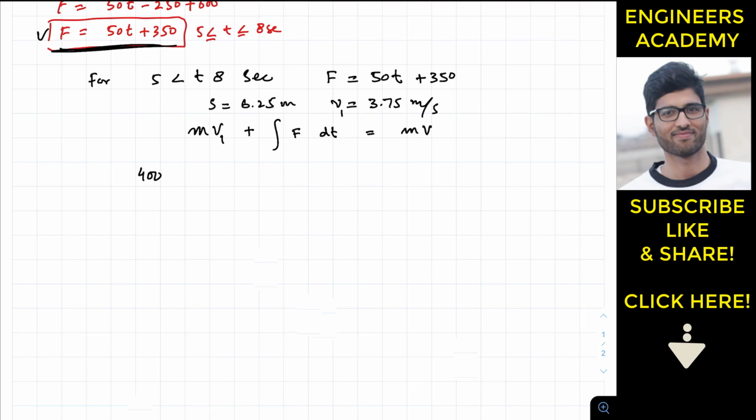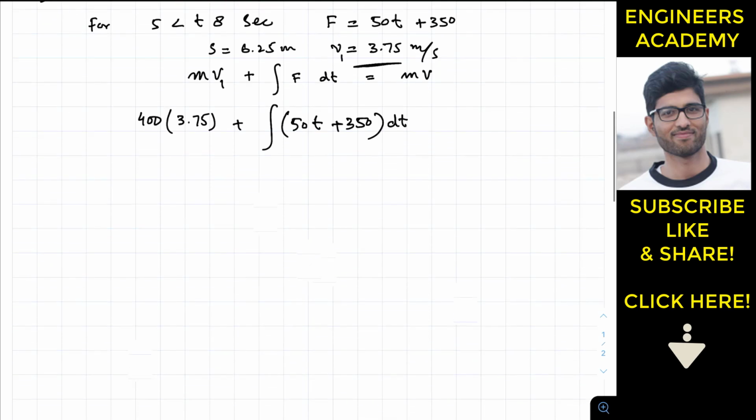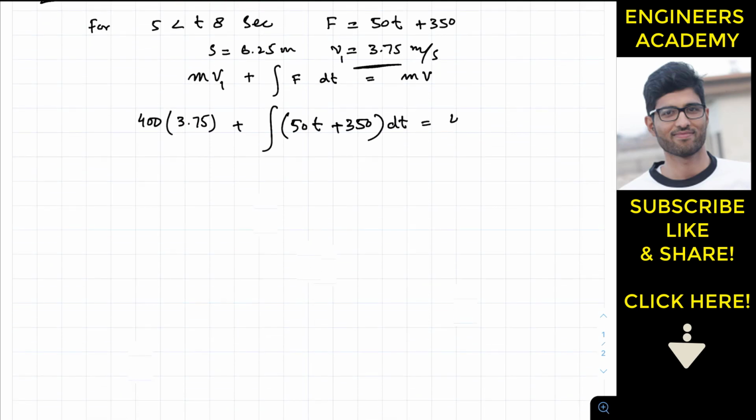So now mass is 400, v1 is 3.75, we have determined this, plus the integral, and now f is a function of time, which is 50t plus 350 into dt, and this is equal to mass 400 into v. So 400 into 3.75 gives me 1500, plus, and now we have to integrate this from 5 to t.